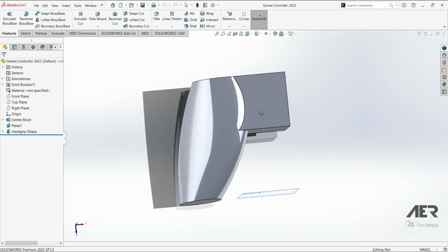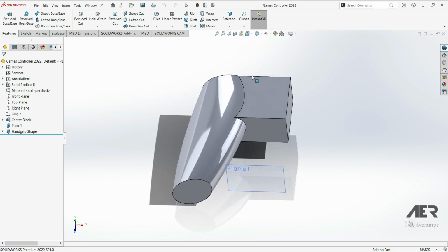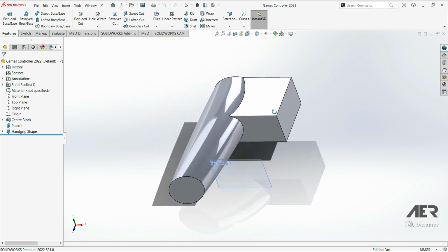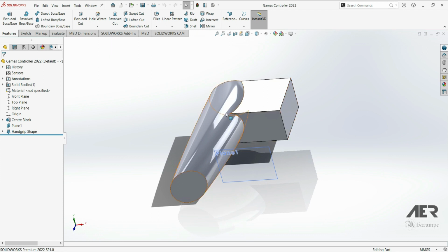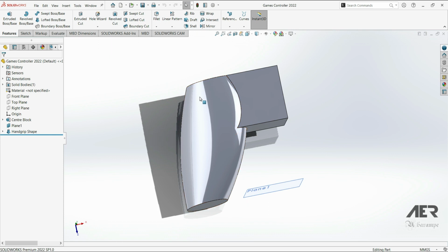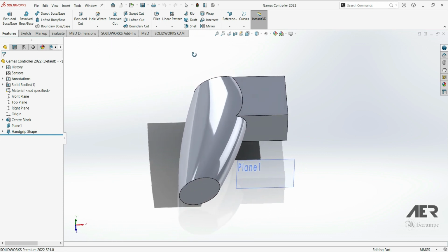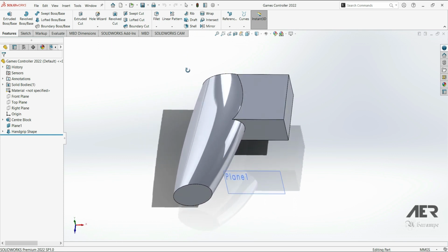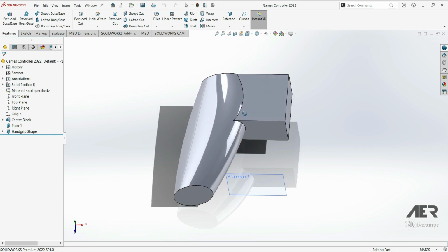But we could also add some guide curves. This might not really be needed in this case, but we are going to have a look at it anyway, just for the practice. To add the guide curves, first we are going to split the loft feature up into the sketches that make it up. So expand the loft feature so you can see the sketches underneath it. And then grab the rollback bar and drag it up so it's above those three sketches, but it's below the